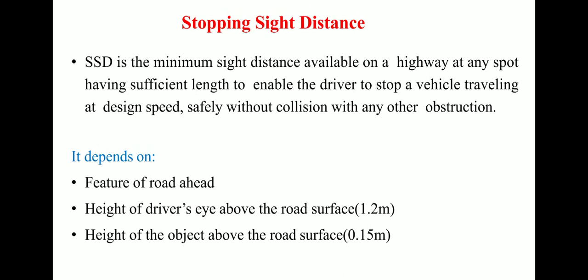Or else we can say it is the distance needed for the driver to see any object on the roadway. The distances are derived for various design speeds based on assumptions for the driver's reaction time, the braking ability of most vehicles under wet pavement conditions, and the friction provided by most pavement surfaces, assuming good tires.